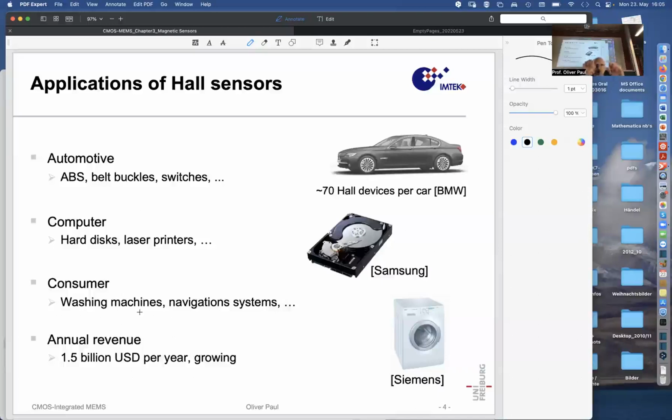Again, there are lots of switches that should be well protected against humidity. A washing machine is a humid environment, and any electromechanical switch that operates by causing an electrical contact between two metallic surfaces to let a current flow, to switch on the washing machine for instance, is prone to degradation and corrosion. At some point there will be so much corrosion that there will be no current flowing anymore. Then you need to replace the switch.